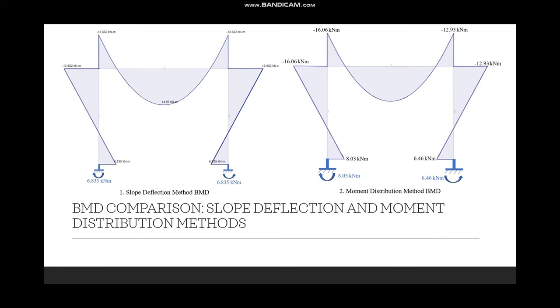And it's the same thing with the bending moment diagrams. We can see that there is more bending moment on the wood than there is on the steel. And also, from the slope deflection, we can see that, again, it's a very symmetrical model, but the values still fall within the same range. Very similar. And also the reaction here is going to be different because there is more moment on that wooden member.